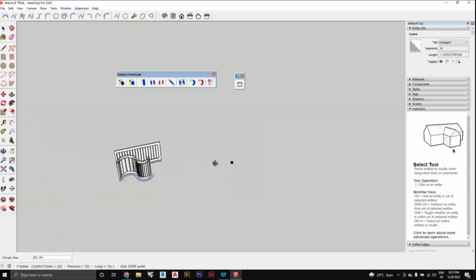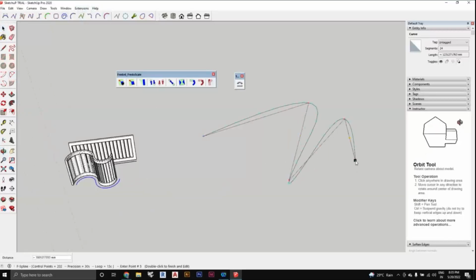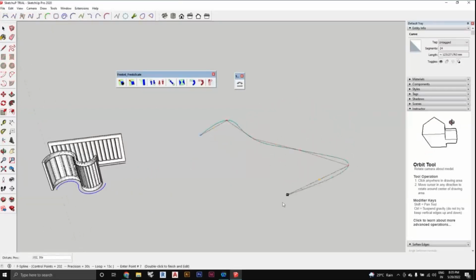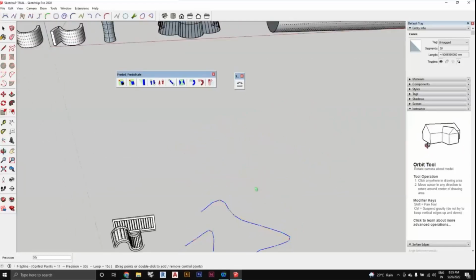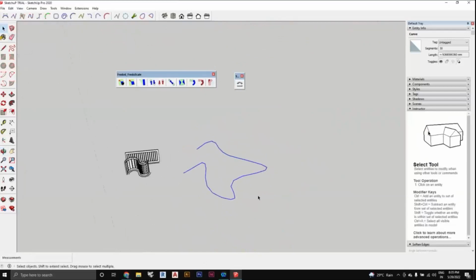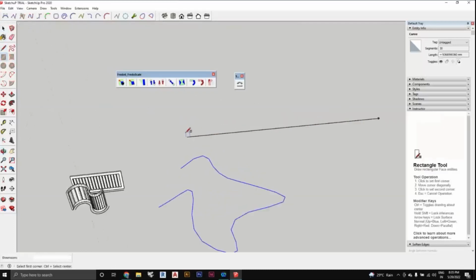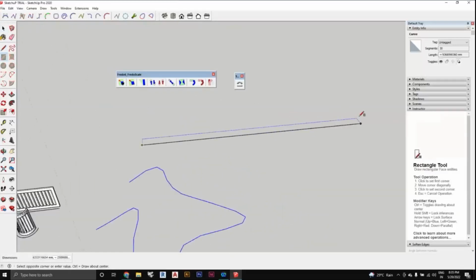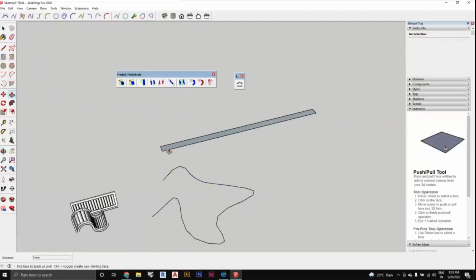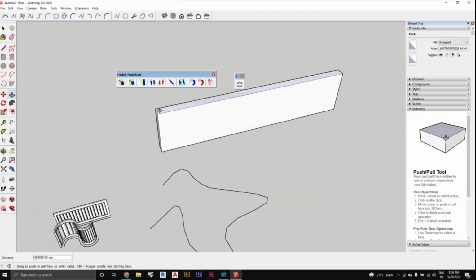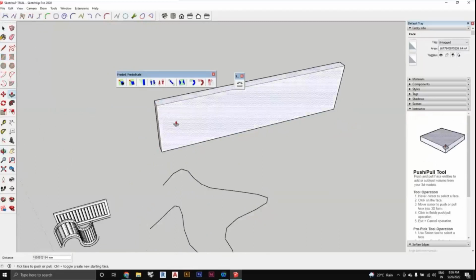If I have a spline, I'm creating a curve like this, and I have a curved wall like this. What I need to do is check how long this length is, and create a line of that length. Then create a straight wall in that length, which is 230 mm depth, and extrude it to the height that you want, like 3000 mm or so.